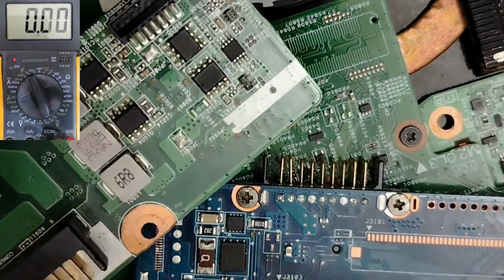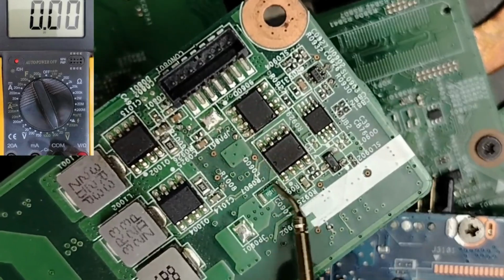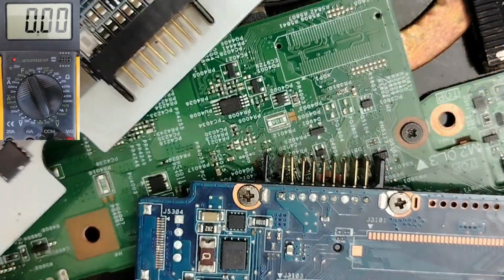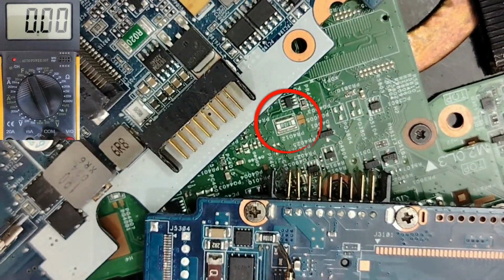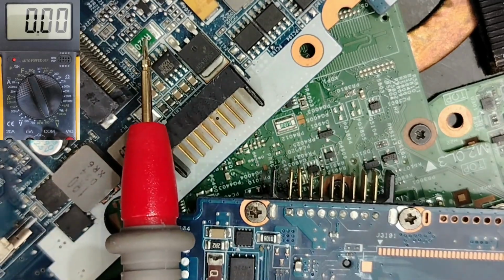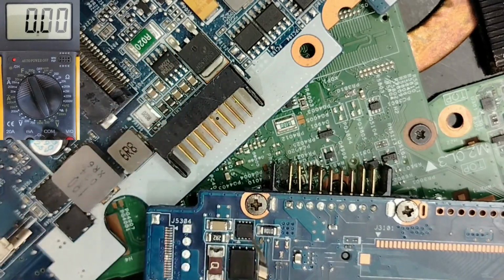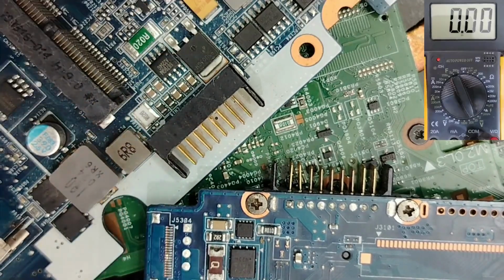We have another board here. Do you see, guys? Let's zoom in a little bit. Do you see? We have R010 current sense resistor. Another motherboard, guys, a very clear motherboard, we have R020, the same. 010, 020, always this is the current sense resistor. So how do we check those current sense resistors? Let's check this one, and this one. I will show you how to test it, because if the current sense resistor is damaged, the 19 volt will stop here. It will stop on this side. It will not pass to the other side, so it will not be distributed to the circuits of the motherboard, including the 3 volt, 5 volt circuit, RAM circuit, CPU circuit, etc.